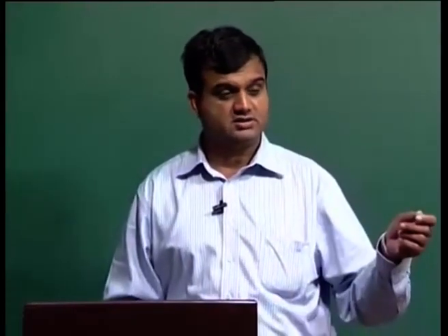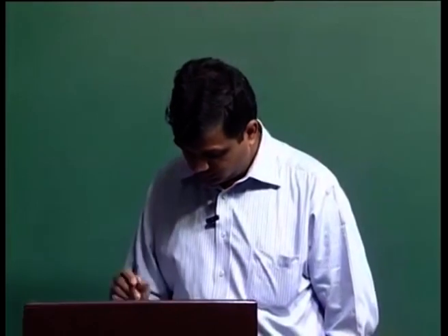Suppose a system which is linear in nature is receiving a frequency input of x1 hertz at a certain amplitude level, and it gives me a certain output response, and then it is receiving another input at x2 hertz, which is different in frequency, and it gives me another response. Then if I sum up x1 plus x2, the response, that is the output, will be a summation of the individual outputs. So this comes in very handy, and we also use this idea in the context of transfer functions, which we will learn later today itself.